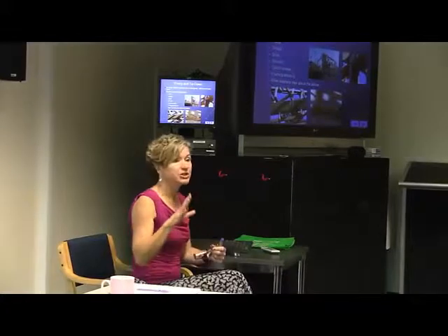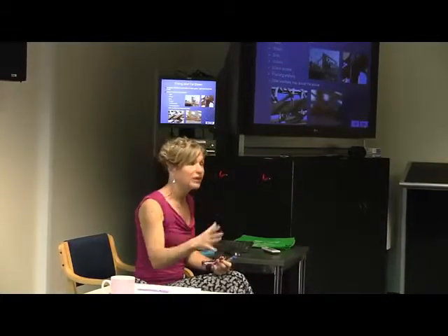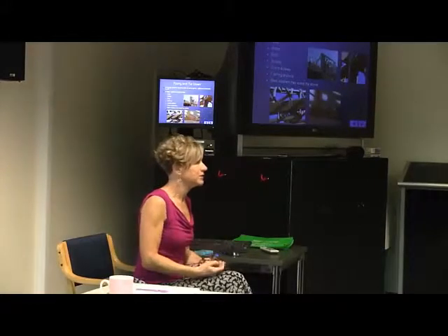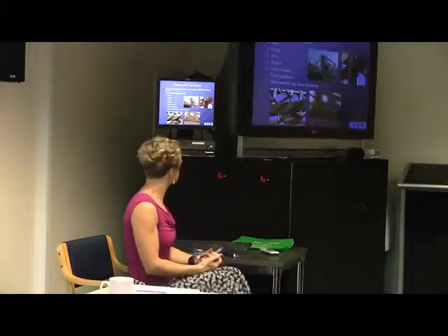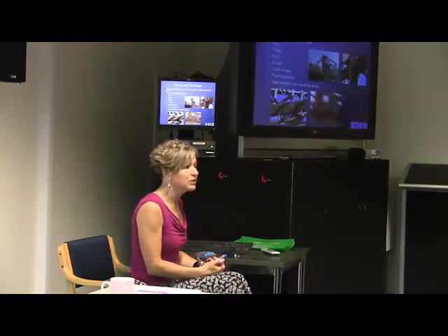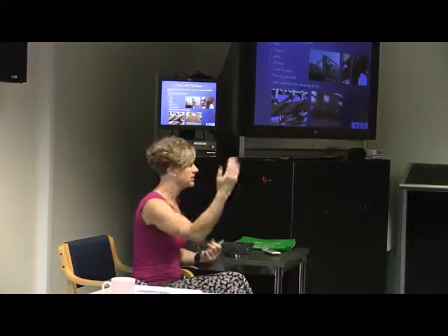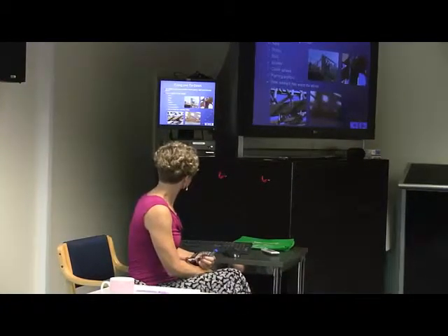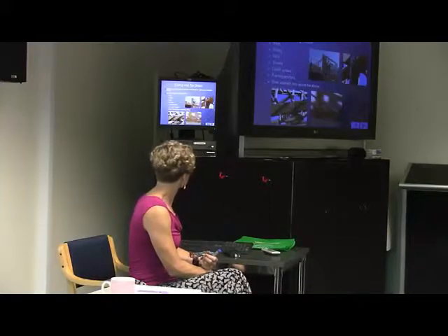So in addition to having those panels that resist it distorting, you need to tie everything down. So there are tie downs, fixings required along with your bracing in order to make sure that things don't still topple over. So all fixings at joints must be able to resist gravity uplift and horizontal forces.